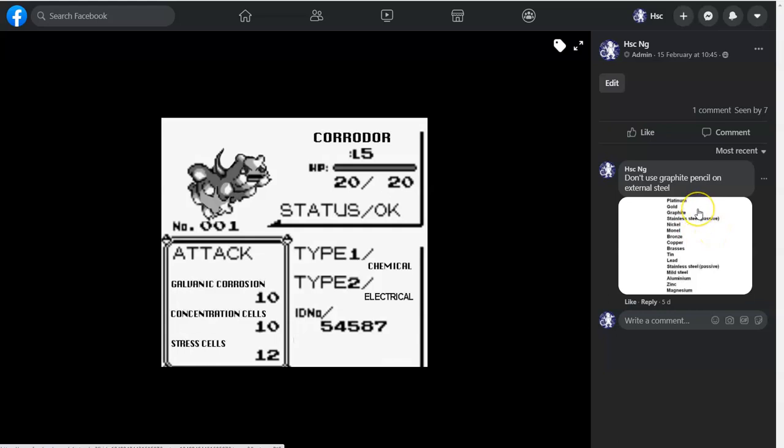Now, they will not necessarily label the galvanic series for you. That means you have to have some idea where at least some metals are. So if you see gold or platinum, you know that's going to be pretty good. Graphite, also pretty good. On the other hand, if you see aluminium or zinc, or magnesium on the other end, you know those ones are going to be the anodes. So aluminium and zinc, they're the anodes. Copper and gold and graphite and platinum, CGP is how I remember that.